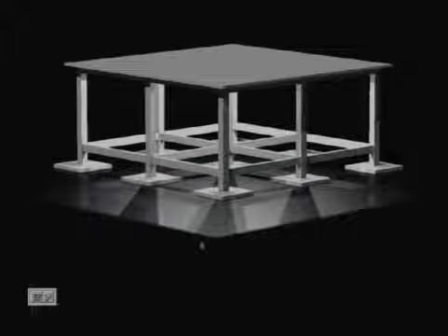We start from the bottom in construction, but when we design we do it the other way, we start from the top. So, slab, then beam, then column, then tie, then footing. This is how the design will proceed. Even if you have a staircase, the staircase has to be designed first. This is just a schematic.